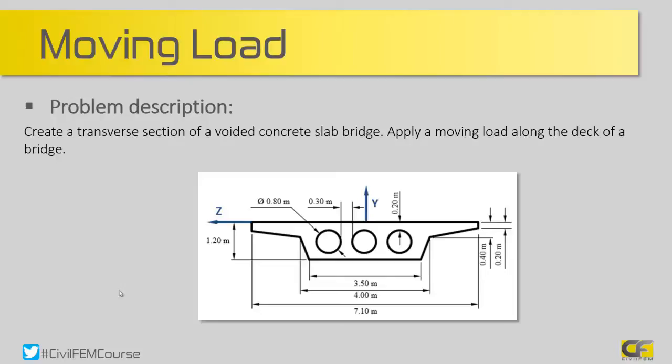The particular thing in this case is that this is not a typical cross-section which is defined in the library, and we will create it just by using 2D modeling in a 3D analysis. For this particular cross-section we have to use the local X and Y model definition or geometry, and then capture this section in this coordinate system to use it to mesh beam elements. So I will create it.